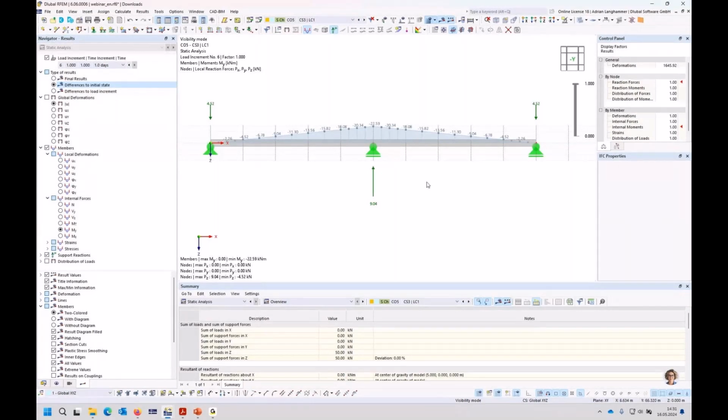So this allows to consider the long-term deformation or long-term effects much more exactly here with TDA. And it allows, for example, also that you could apply additional loads during the construction process, and you could consider individual long-term behaviors for all these applied loads separately.